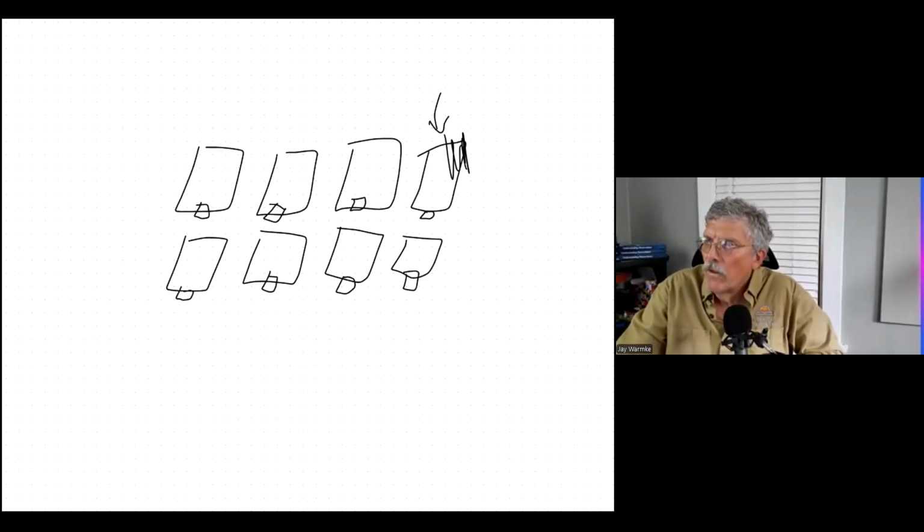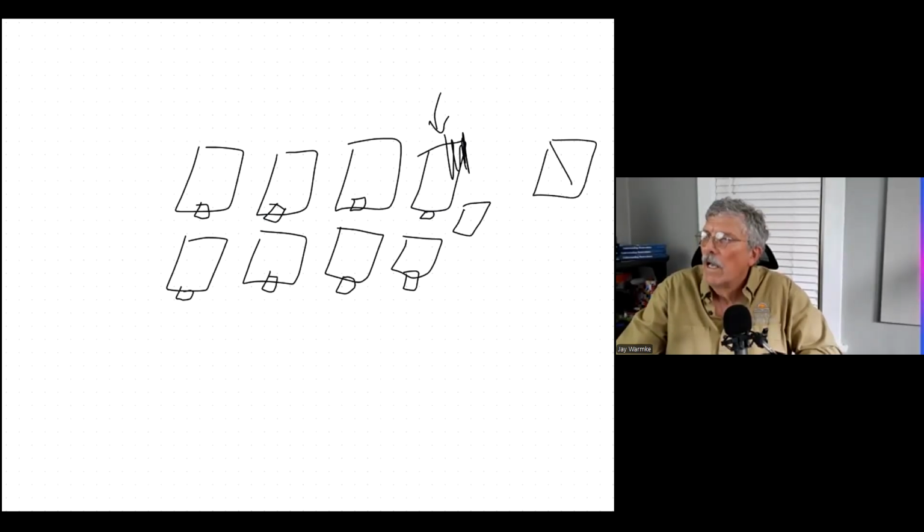The reason we used to do combiner boxes was just to save wire. But the power output is more valuable than the wire. So we tend to now not use combiner boxes. We'll oftentimes use junction boxes. So let's say we have this box and we still have a string inverter with a DC disconnect. Oftentimes you'll have the strings coming in, a string coming in here.